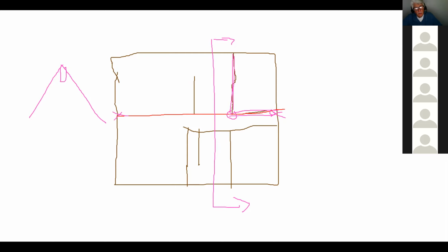You have to go into the roof space and see if this beam that you have at the roof space is sitting right above that beam that you want to modify. So you have to go and check to see how this beam is being supported. In other words, if we do a roof plan, this is my roof plan. Here's my beam. Here's my rafters that are going down. I have to determine, do I have a column only there and there? If that's the case, then you know there's no load from the roof coming down onto that beam. Okay, that's number one. But at least we know that there's loads coming here. But you might not have to modify that column.